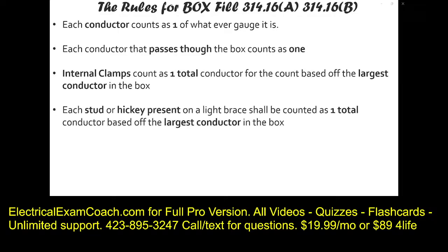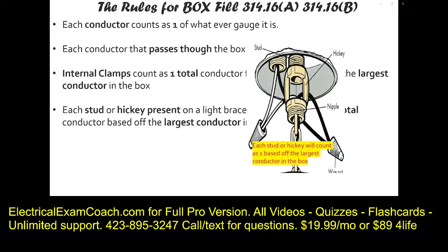Next, each stud or hickey that is present in the box shall count as one total based off the largest conductor that's in the box. Now, these are really old words, probably from the 30s if I had to imagine, but they still use them on examinations today. And this is what we're talking about. Imagine that we're hanging a chandelier. This we would call the stud or the nipple. Or, this would be the nipple. But they're calling this the stud and this a hickey. And they still use this terminology on exams today, so you definitely need to understand.